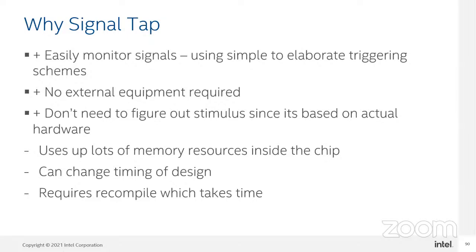Because of that, it won't affect the functionality. Your design will still work like the same design, but the drawback is that it will affect the timing of the design. It can change the timing and it requires recompiling, which takes time. After integrating your embedded logic analyzer into the system, you need to recompile the design again. Any modification or change you make, you have to recompile the design, which will take time.